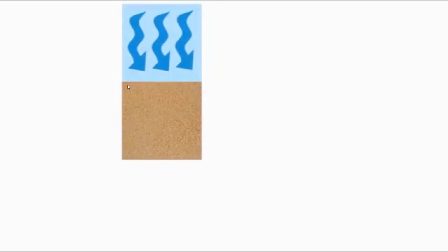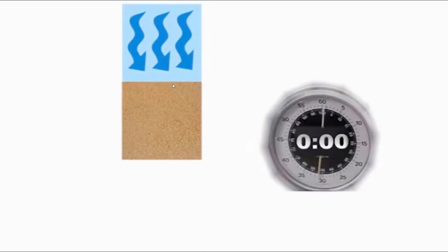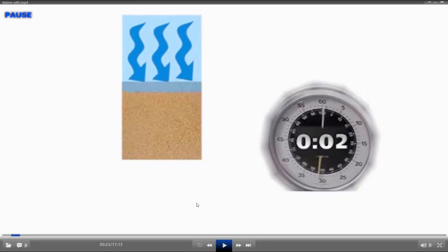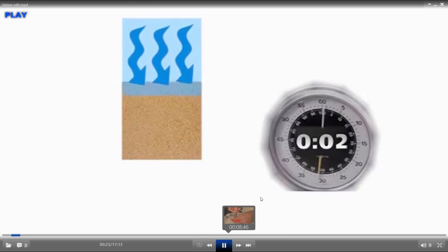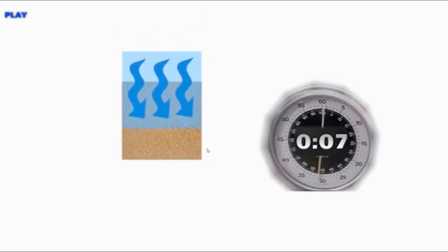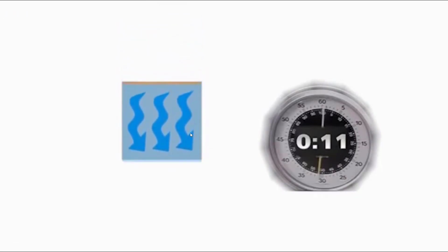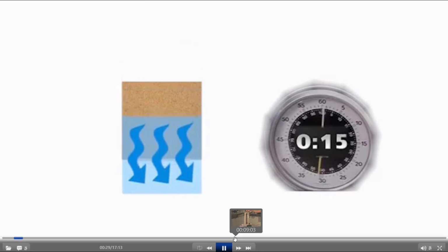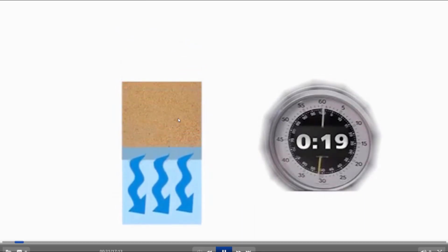Basically, this is a cement column, a cement confined column, which is confined by the plunger on the one hand and the perforated tube on the other hand. The air is passed through this cement column. You just note down the time required for a specific portion of air to pass through this cement column.